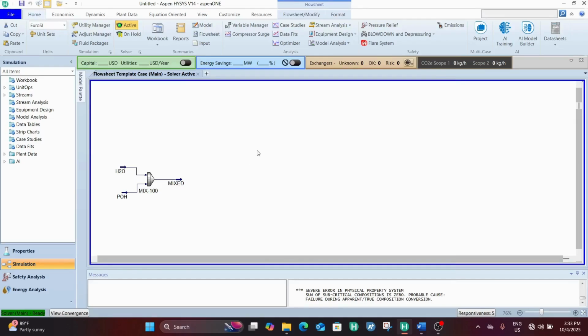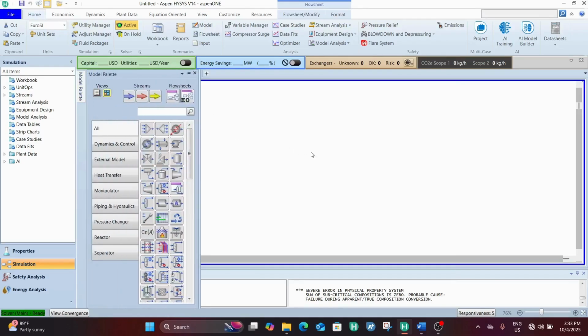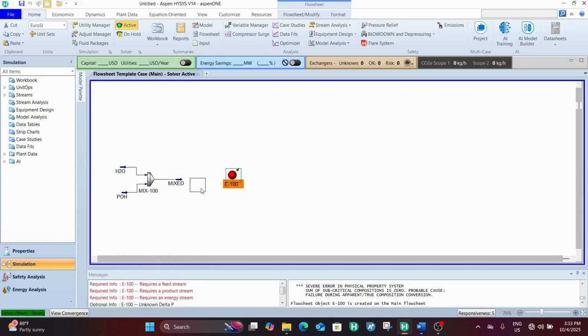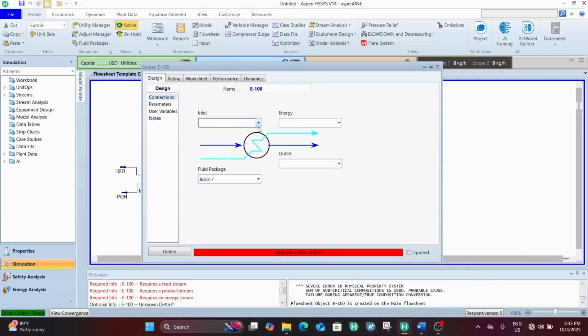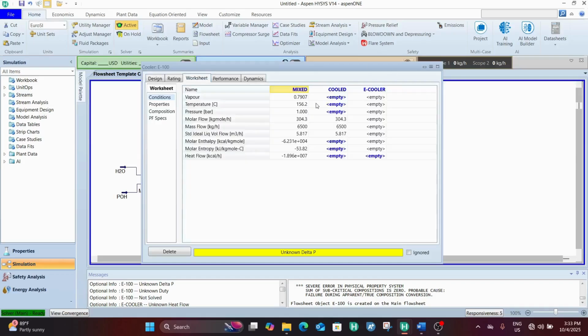So we could just work with 80, I think. And to do that, we need to drop our temperature, and equipment that drop our temperature include coolers, heat exchangers, refrigeration cycle. We could just work with a cooler to keep things simple for the design. I'm not really here to use a heat exchanger because it's energy efficient. So plug this in, call this e-cooler, cool, and specify the change in pressure.